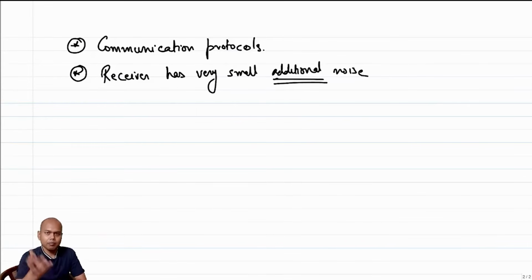There is probably some air blowing; even in the most silent of environments, there will be some datum level of sound that you will experience. If nothing external, you are probably going to experience the sound of your breath, for example, so that is an additional noise. So when you are designing a receiver circuit, you have to ensure that the amount of noise that the receiver circuit itself is generating is sufficiently small.